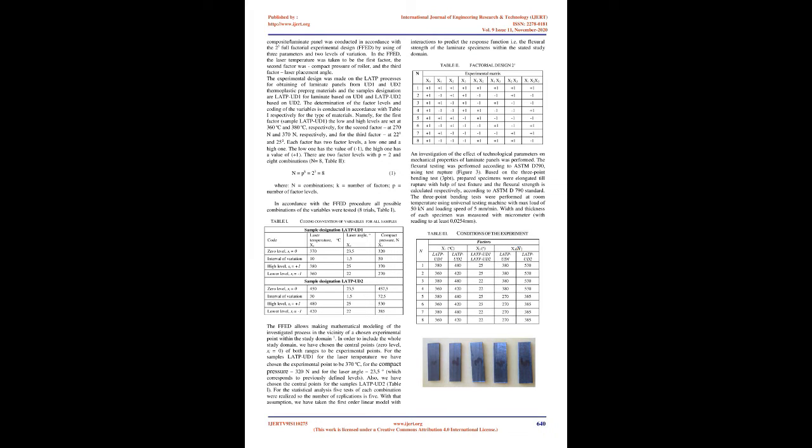There are a number of parameters that affect the quality of the final TPC in the AFP process, which influence the thermoplastic composite's mechanical properties [3 to 6]. Welding of semi-crystalline thermoplastic UD tapes with LATP, laser-assisted tape placement, is analyzed in many literatures as well. These studies have led researchers to attempt to measure the temperature distribution near the weld process zone [3 to 18]. The thermal history of the composite material during processing by LATP is of great benefit to understanding bond quality and the properties that control it, e.g., crystallinity, void content.